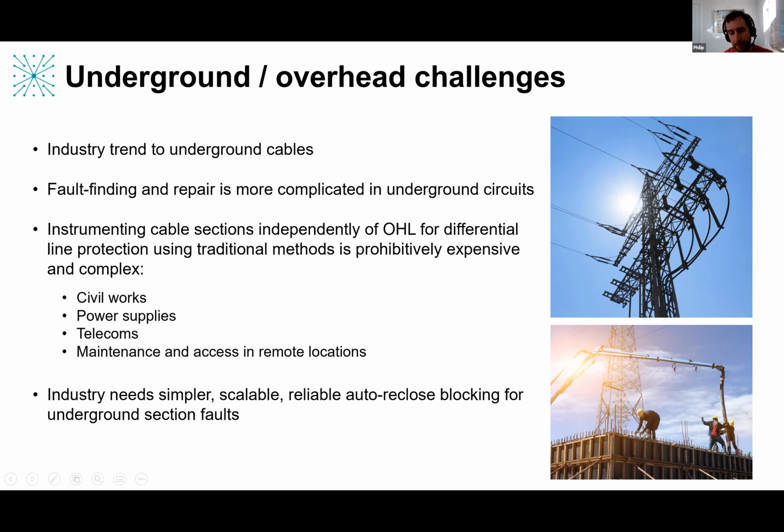Some other sectors, though, in power, but say offshore and renewables and so on, they're interested not only in the faulted section, but also what is the reason for the fault and the precursors. And there's been quite a lot of research done on what the common failure modes are. Can we identify the common failure mode between the conductor itself and the terminations? And then in those situations, it helps to have a bit more contextual information, rather than simply detecting the fault and knowing how to react, seeing the precursors in advance from mechanical signatures or even electrical transients. So we'll talk a little bit more about that advanced functionality later.